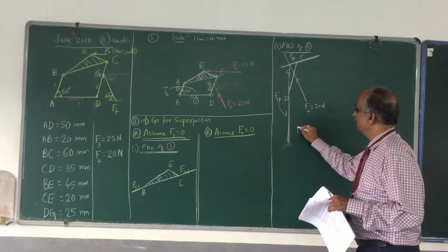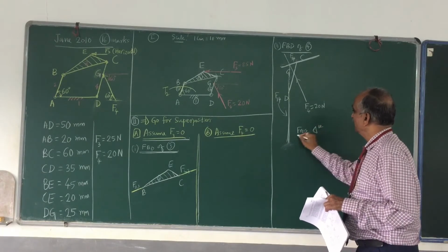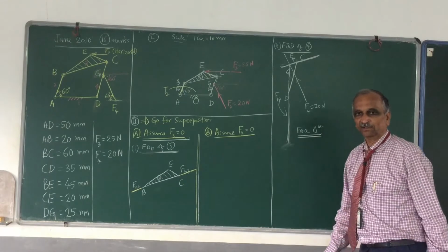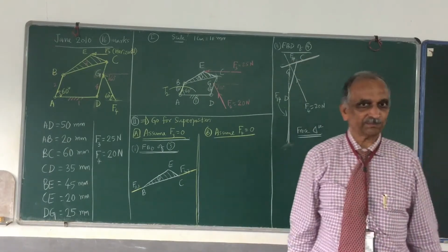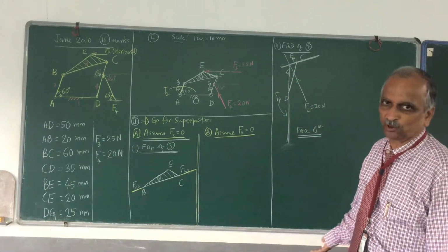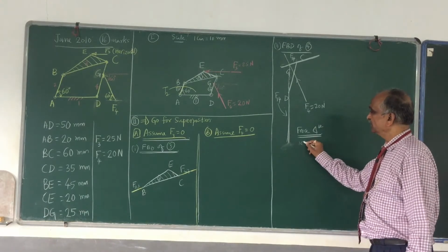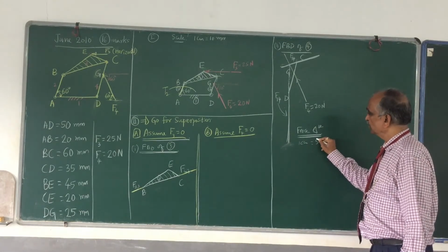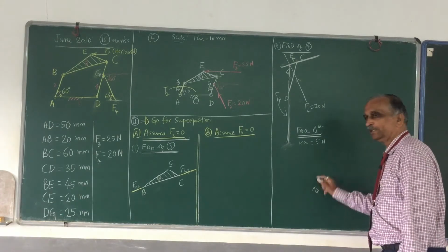Now go for what is called the force triangle. I want to draw the force triangle. Why a force triangle? Because it is an equilibrium. The resultant must be 0. If the resultant has to be 0, the polygon will be closed. In this case it is a triangle. Choose a scale K, say 1 centimeter equals 5 Newton. So I shall choose a point, this is the point.